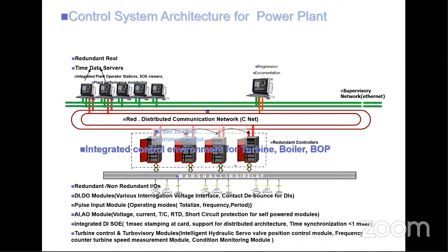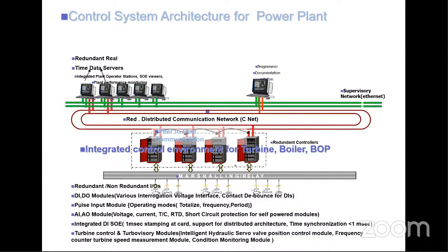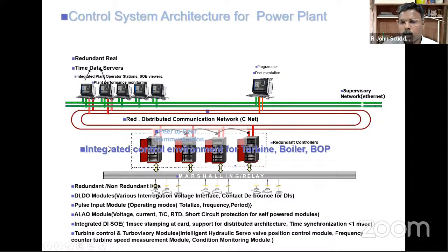You told one thing, sir, that ADC part. Where is the ADC placed, in the junction box or in the DCS nodes? Inside the DCS nodes. Those digital signals are transferred by means of a LAN to the engineering stations, right? No. In the control network, all these things happen only to the operator workstation, that is the graphical HMI. For that reason only, we are using the LAN.